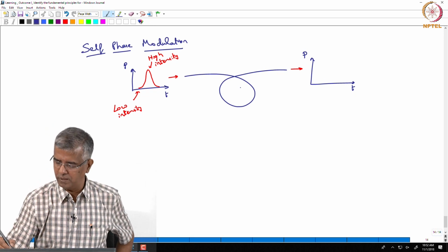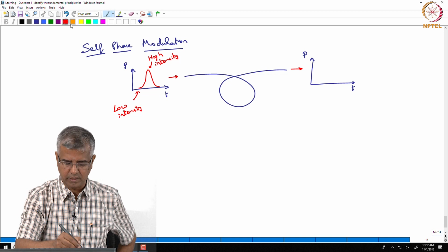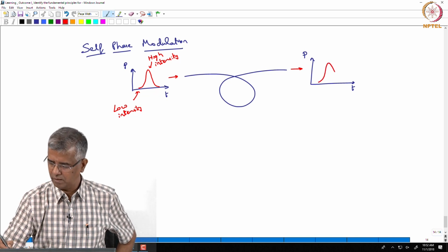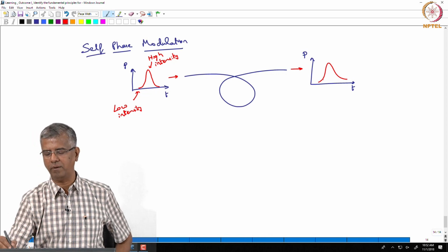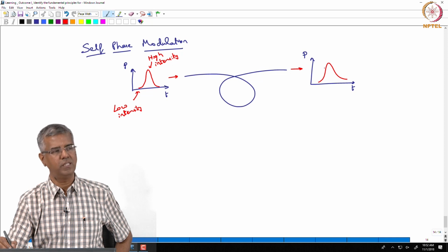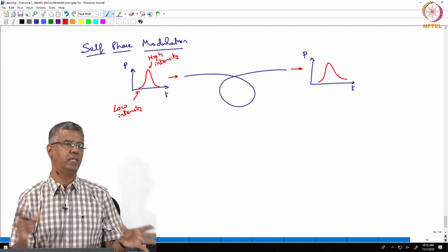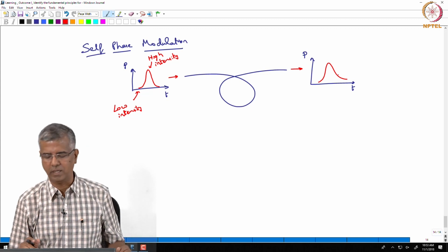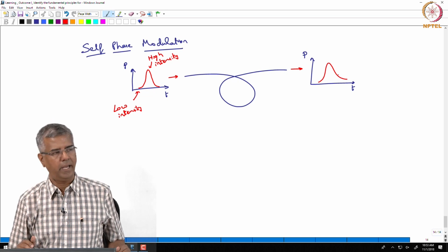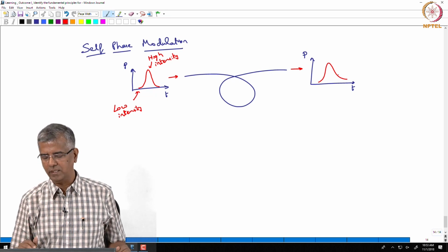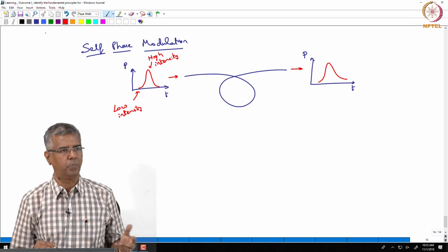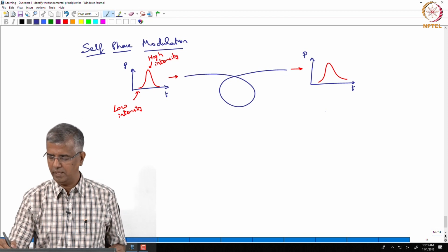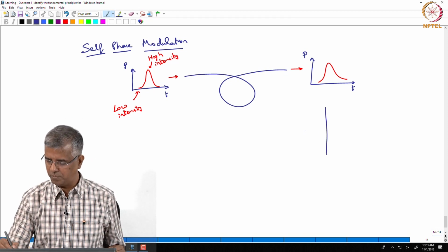So, your output pulse is not going to look like this, rather, I am just going to exaggerate it, but it is going to have some high frequency components and some low frequency components. It is essentially going to go through some phase distortion, and that distortion now is actually generating new components, right. We are running out of time, so I will just stop with this thought.